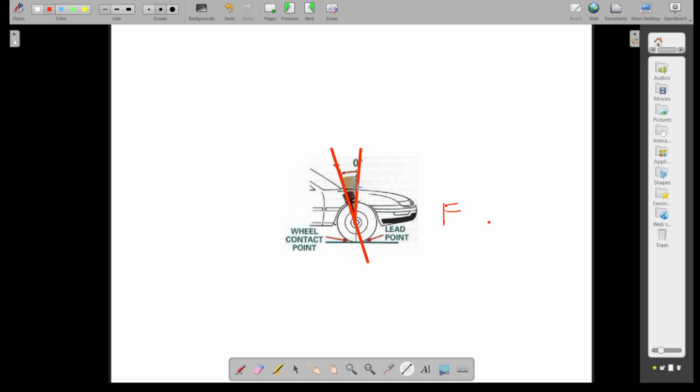See, if you have driven a vehicle, you know that when you rotate the steering wheel, you can find that the steering wheel comes back to its original position again. This is achieved due to the caster. It also reduces the steering effort. Generally the caster is kept in between 2 to 7 degrees.